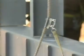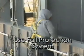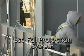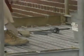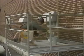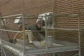When working on a scaffold that is elevated at 6 feet or more, a fall protection system, such as a safety harness and lanyard, must be used. The lanyard must be attached to the structure itself or a securely rigged lifeline. Finally, before a scaffold is used as a work platform, it must be clear of tools, materials, debris, and ice, snow, or other slipping or tripping hazards.